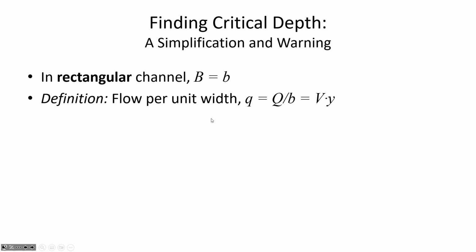You wouldn't calculate flow per unit width here because this part of the channel is carrying less per unit width than the rectangular section. Those edge pieces don't have the same capacity, both because the depth is changing, but then also there's the issue of them being closer to where the resistance is applied with the shear stress.